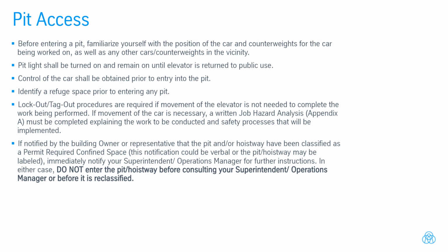If notified by the building owner or representative that the pit and/or hoistway have been classified as a permit-required confined space, this notification could be verbal or the pit or hoistway may be labeled. Immediately notify your superintendent/operations manager for further instructions. In either case, do not enter the pit or hoistway before consulting your superintendent/operations manager or before it is reclassified.